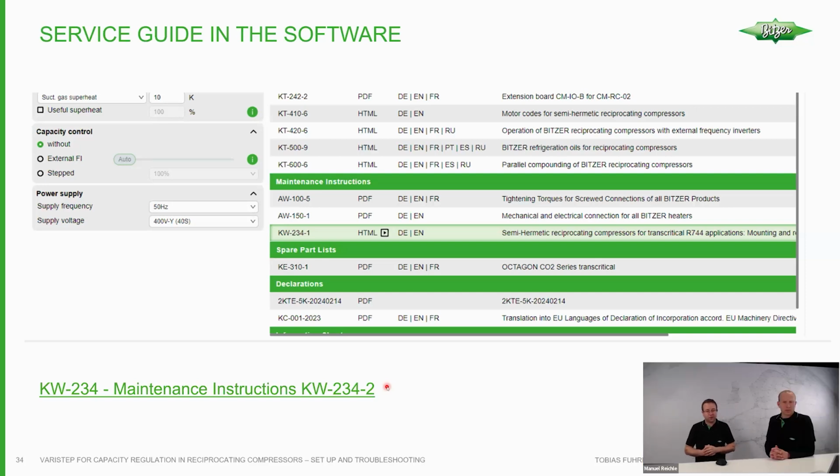Yeah, the sound changes because we go from basically a 4-cylinder operation to a 2-cylinder operation. So the compressor configuration gets a little bit imbalanced. We try to make it as balanced as possible also for the unloaded situation, but the reaction of the compressor from its vibration to the system is changing, and therefore you can also have noises, of course.